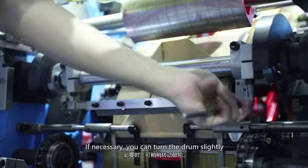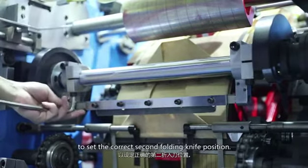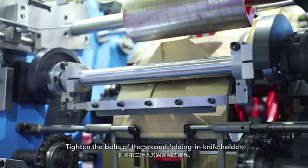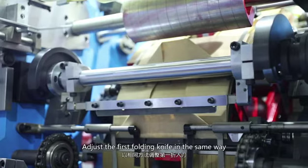If necessary, you can turn the drum slightly to set the correct second folding knife position. Tighten the bolts of the second folding knife holder. Adjust the first folding knife in the same way.